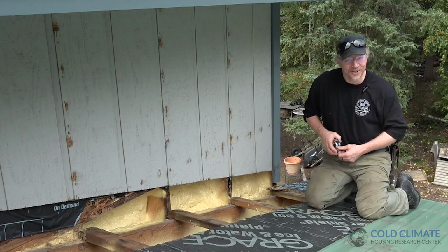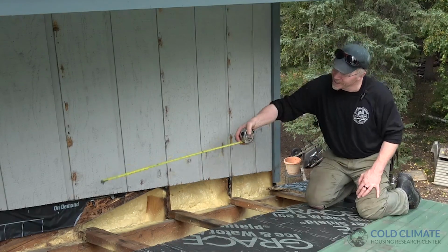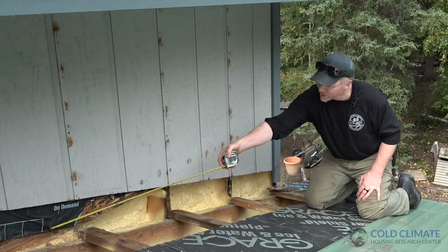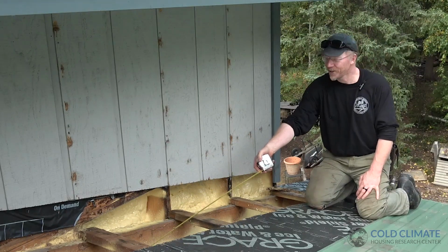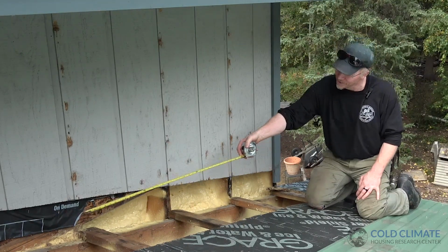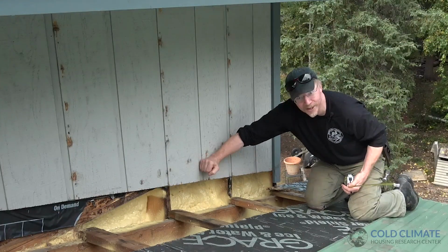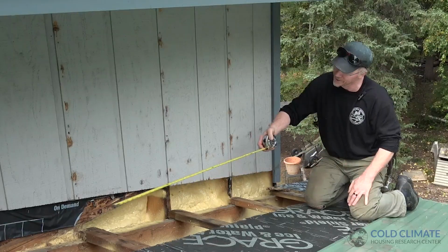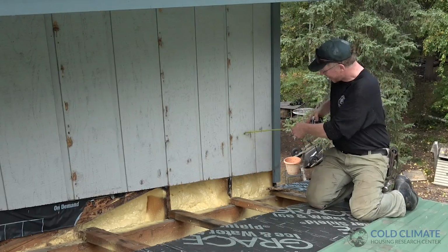What's also really interesting is we have another manifestation of that air leakage driven thermal bypass, where we have a wall that changes from an interior wall to an exterior wall. You can see this right here. Here's the old house roof. Here's the new house bathroom wall. The bathroom is against an exterior wall, and the plates run all the way along here.